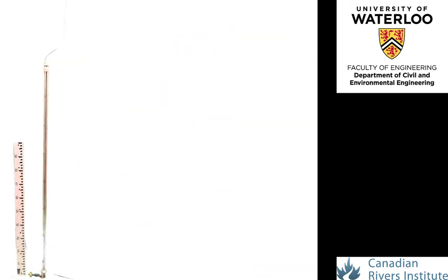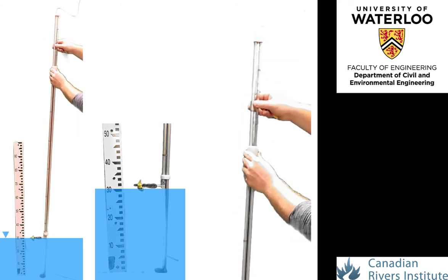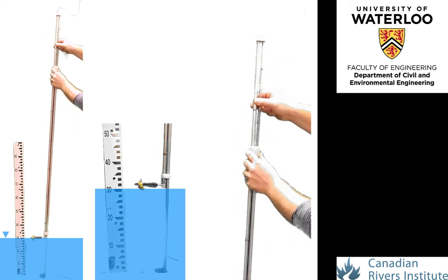The use of the top-set rod is demonstrated here using a staff gauge, which is merely a graduated meter plate with a depth of 0 coinciding with the base of the stream bed and the values increasing upward, which would coincide with the increasing stage of a river. A flow depth of 30 centimeters is shown. When the flow meter sits at the bottom of the rod, the top of the sliding rod rests at the top-set reference location. The sliding rod is raised to the water surface, in other words, until the center line of the flow meter axis corresponds with the water surface.